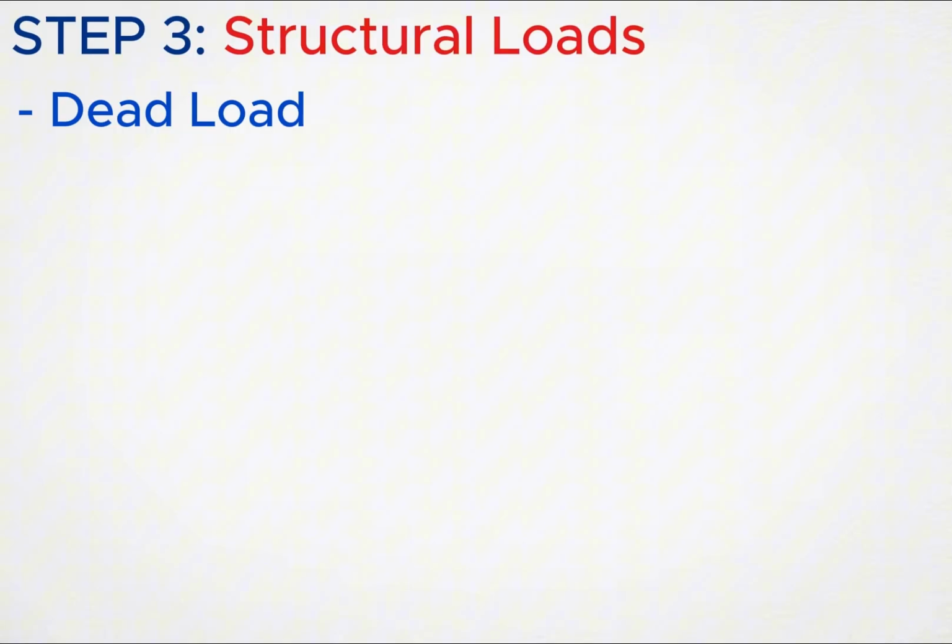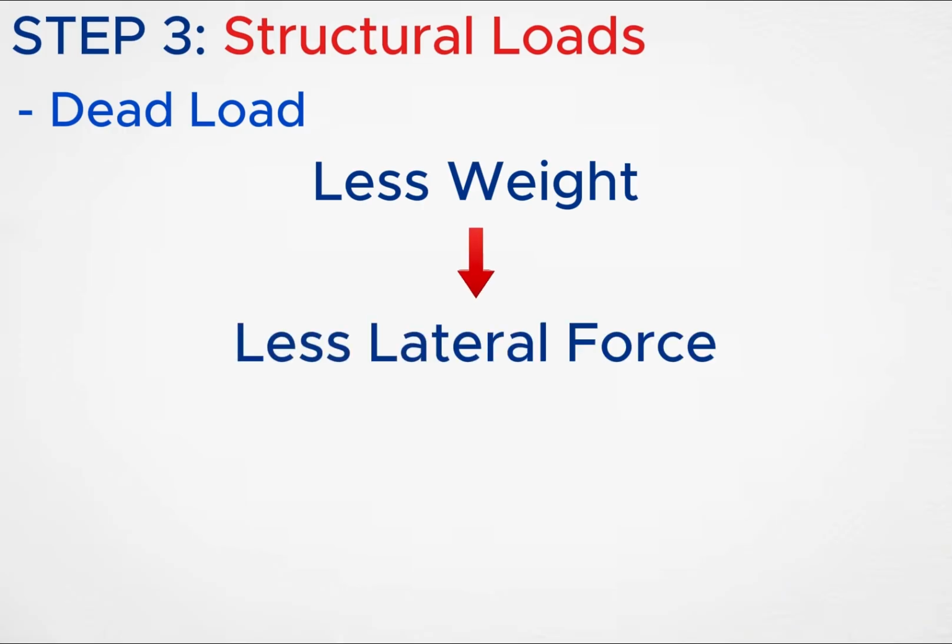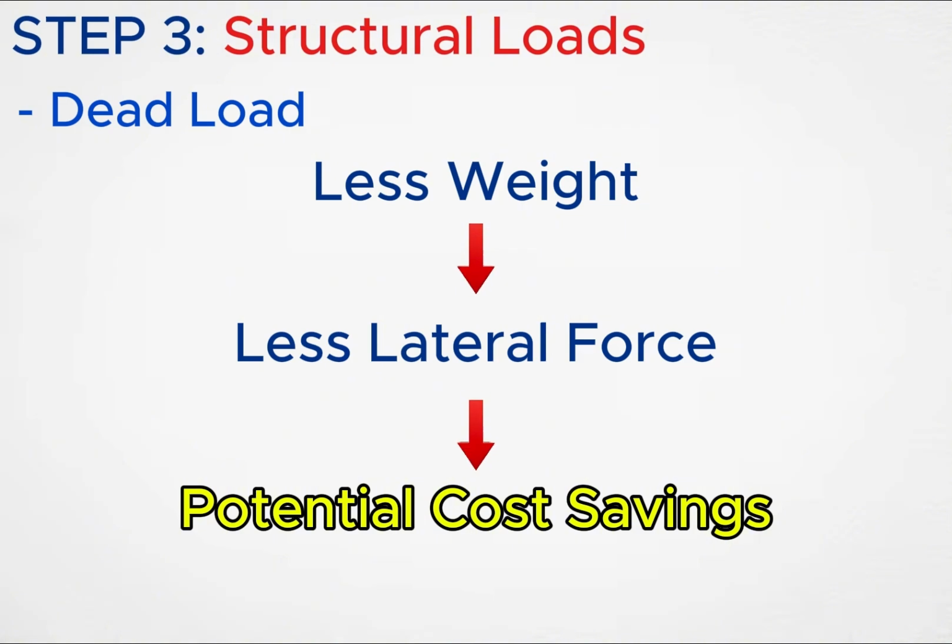And here's an important design concept. Reducing dead load doesn't just reduce gravity loads. It can also reduce lateral forces from wind and earthquakes. That's one reason residential structures often use lightweight materials whenever practical. Less weight, smaller lateral forces, and potentially lower construction costs. As engineers, we don't just calculate loads. We also think about how design choices affect those loads.